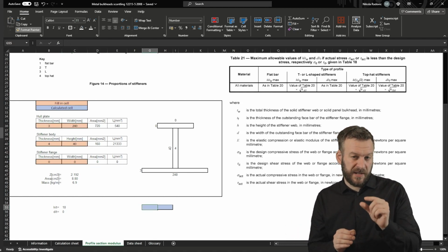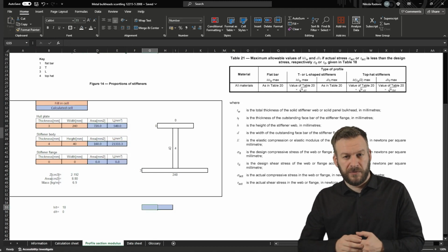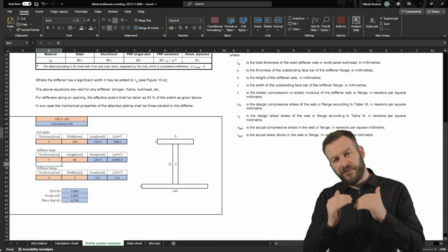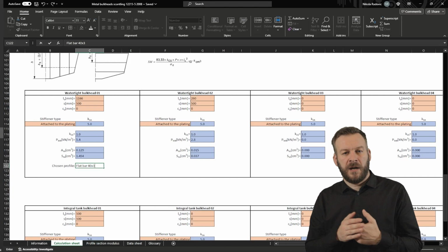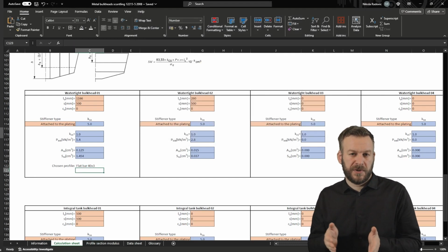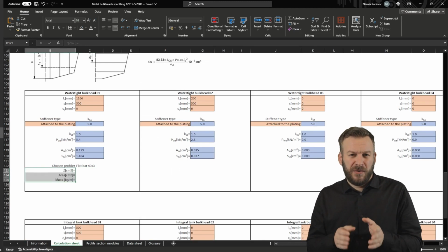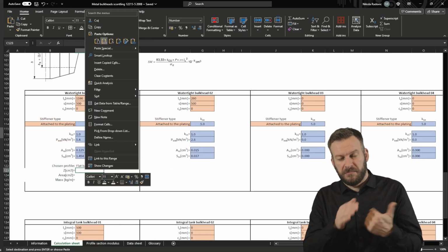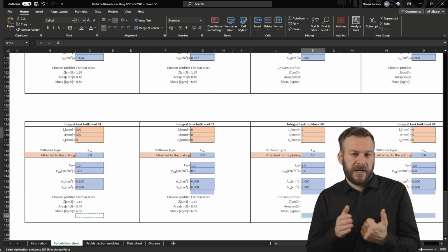Now, as I said, first type in the plate thickness and width of plate that should be taken into account when we are calculating section modulus. And then I will change dimensions of the profile until I find one that satisfies our needs. And it looks like a flat bar of 40 × 3 mm fits our requirements. I will now fill in the chosen profile and calculated values of section modulus and area in the main tab of the spreadsheet. And I will repeat that for other bulkheads.